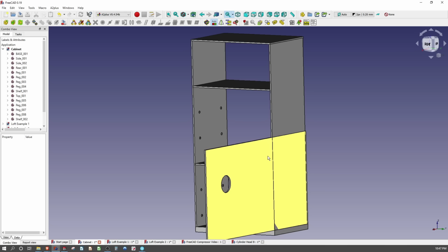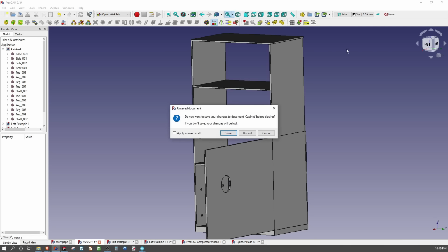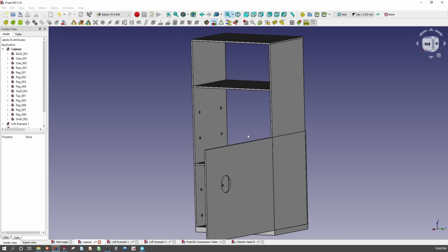All CAD platforms register errors when there's redundant constraints, but platforms like Alibre, SolidWorks, and so on have good algorithms that make it so it's kind of a non-issue. FreeCAD has algorithms that fix some redundant constraint errors as well. They're still under development though, so you will occasionally have some redundant constraint errors, but hopefully that will be developed very well in the coming versions. But as of right now, Alibre adds, I think, a lot of value in being able to handle assemblies.